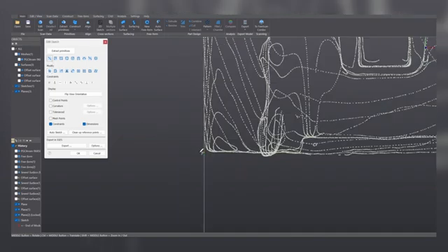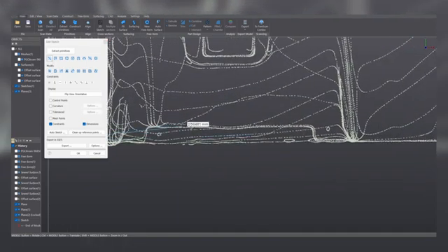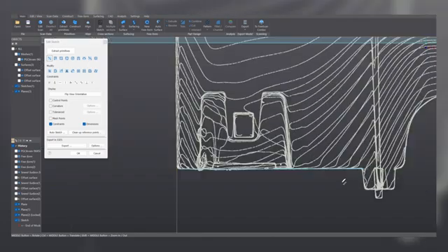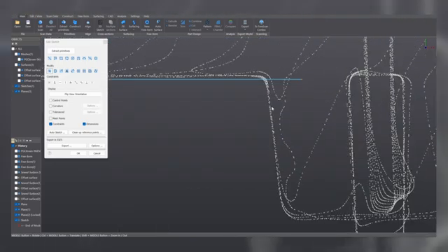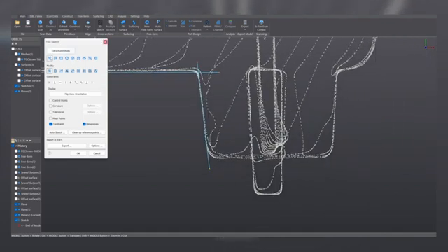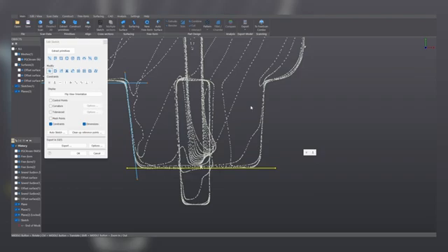Now, what we do is let's start here in the origin. Let's draw a horizontal line like this. Actually, let's click on it and make sure that it's horizontal. And now let's reproduce this geometry. How? Well, with the Shift key and selecting the points, you can quickly best fit lines. Here, actually, I will eyeball one horizontal line on the top of this shape.